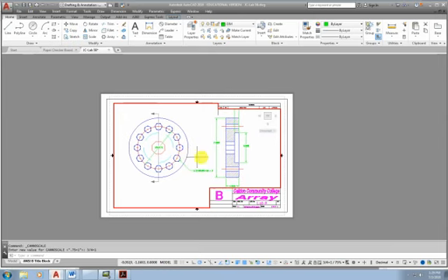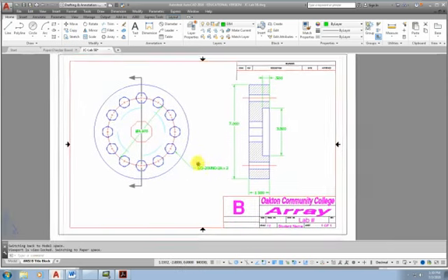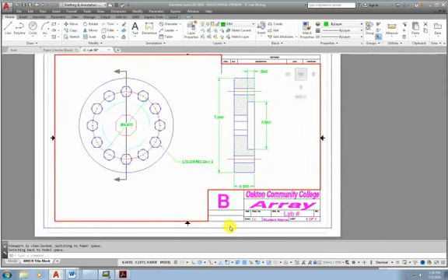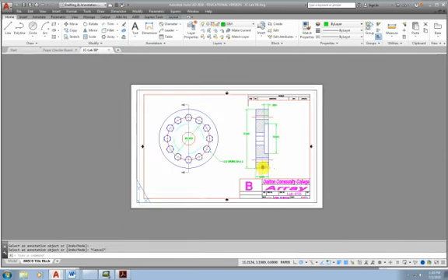And you can see I've got a little bit of work to do to get the dimension to fit in there. I'm going to lock the dimension, and then I'm going to go to model space, and I'm just going to ring this one in a little bit, and then I'm going to come back, and we're good. I'm going to fill out the title block, double click outside of the viewport, and I'll say 3/4 equals 1. Make sure you put your name on it, and double click on that and go to the end, 5B. Okay, so this completes our exercise.